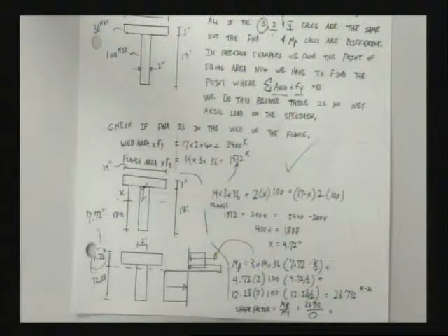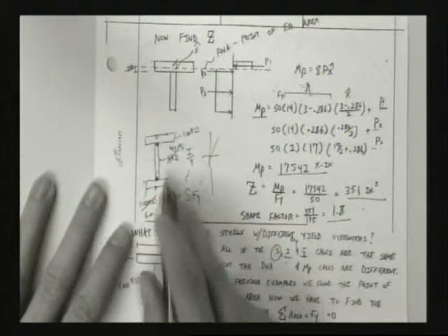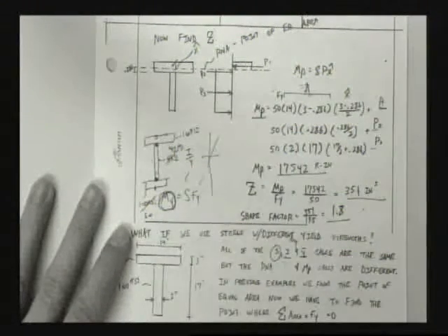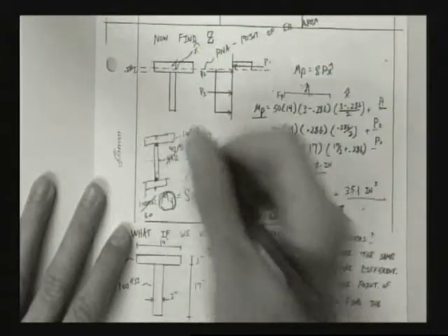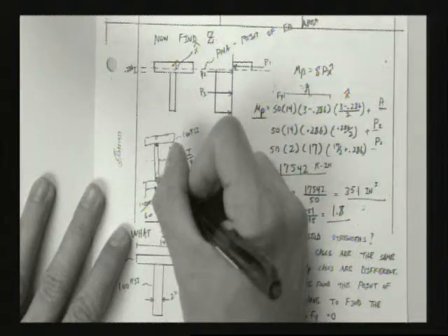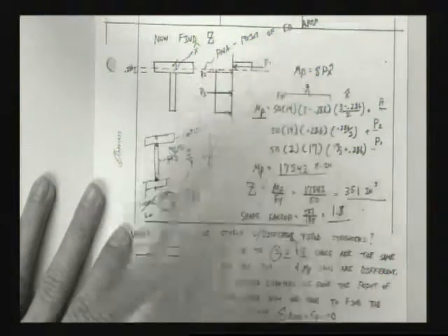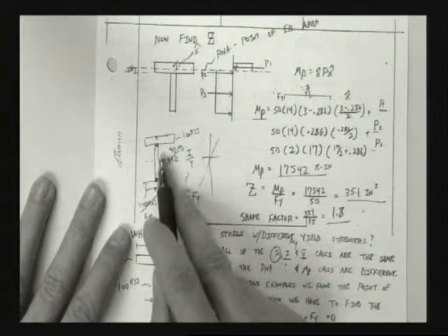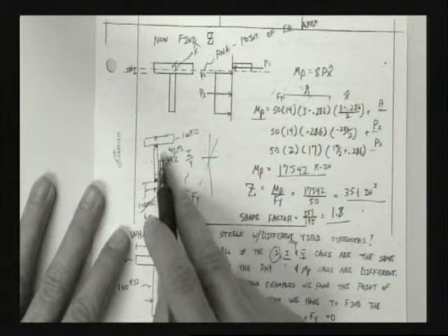Okay? It's coming up. And remember again, when you're trying to find M sub y, how do you do that? You just check at the critical areas. You say, well, what moment does it take to cause this to yield? This to yield? This to yield? Wherever I have changes in cross-sectional area, wherever I have changes in cross-sectional Fy. Okay? And you find the lowest one, and the lowest one wins. Okay? Okay. See ya.